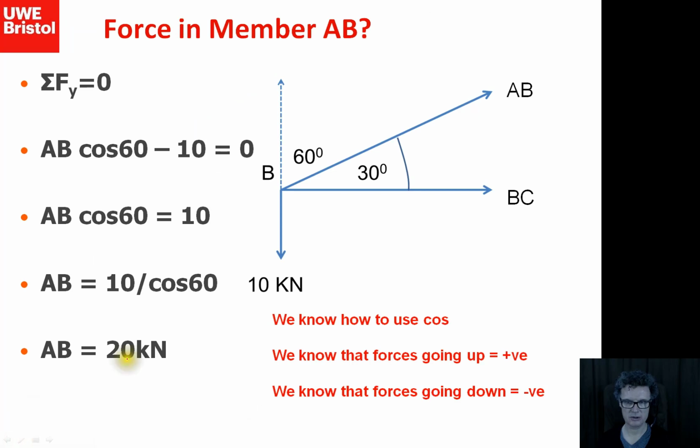And here's the solution. So since we're only looking for the AB, we're only going to bother resolving the forces in the y direction. So I decided to use cos theta, not sine theta. So I worked out what that angle was going to be. Then I swung through my AB so that it pointed vertically.